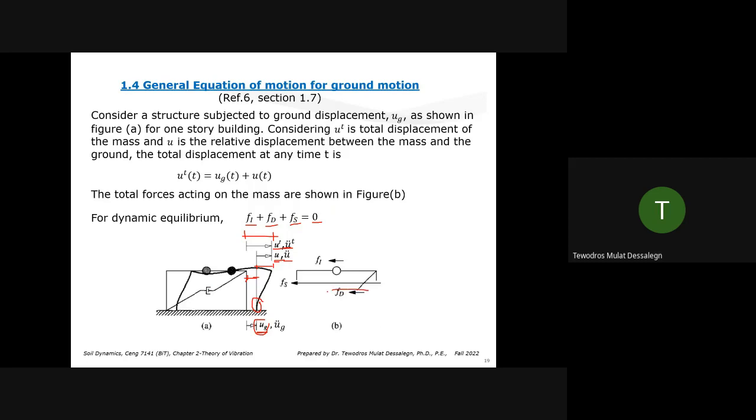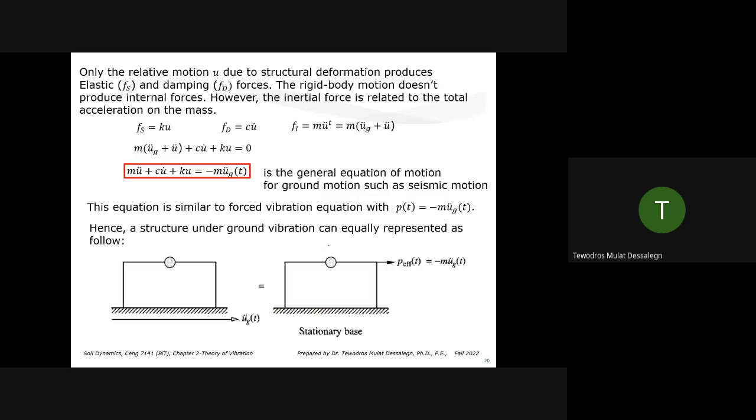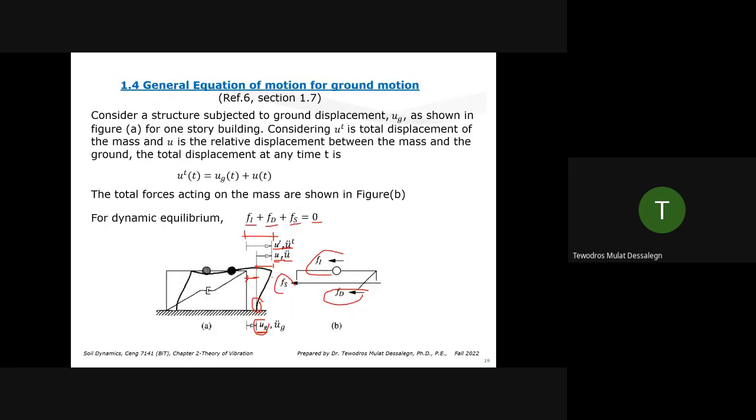So you have the damping force resisting the motion, the stiffness force resisting the motion, and also the inertial force in this direction because the ground moved here. What is felt by the framing members is of two kinds. There is one related to the relative motion, especially the damping force and the stiffness force. These are forces stored within the frame because of the relative motion. If everything moves together with no relative motion, then the structure, the beams and columns, are not going to feel any force.